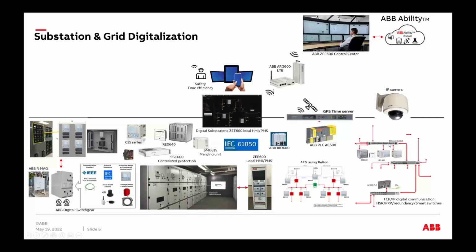At the same time, you're thinking about the real estate. Do I have the real estate that I need to put all those devices? How am I going to put them in the existing panel? And how do I manage my outages? Because you remember, you cannot just shut down the power and work on it until whenever you are done. You have to keep in mind, maybe you work feeder by feeder, depending on how the utility or the end user is going to allow you to do that.